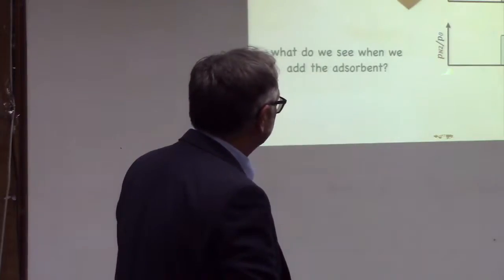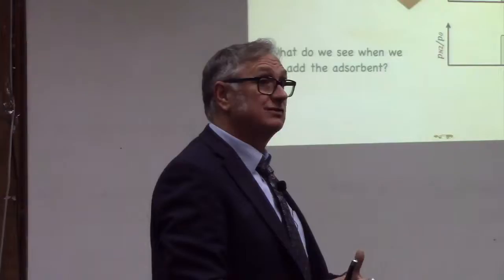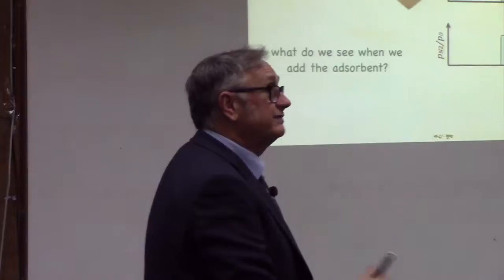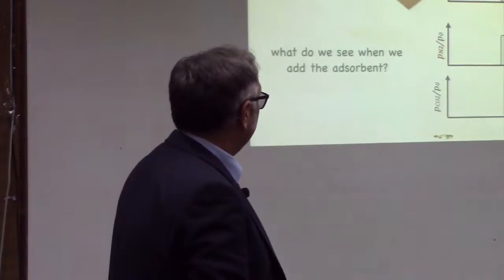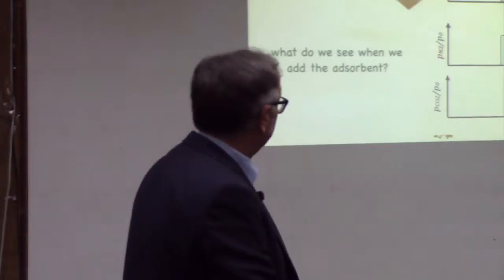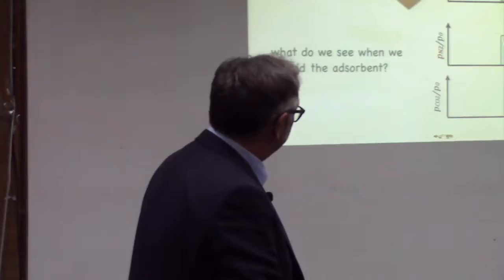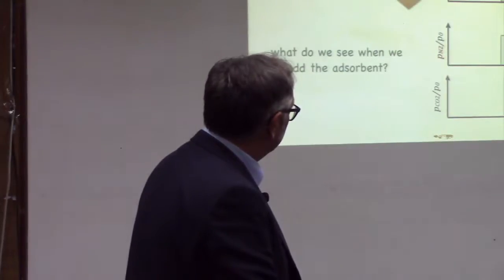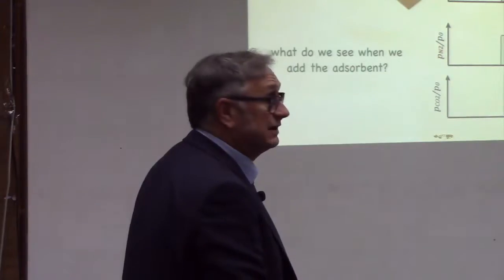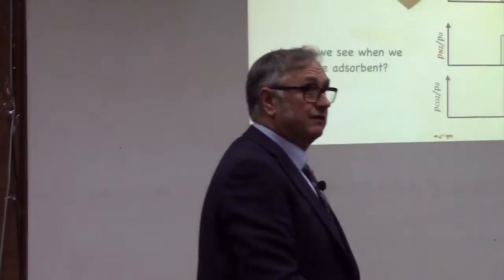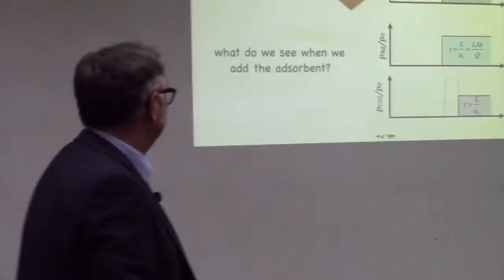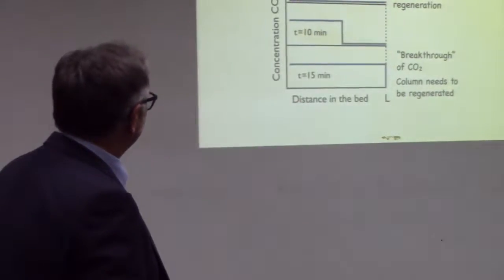Here, for example, is the partial pressure of nitrogen. Nitrogen doesn't adsorb. It passes through just as though there was no powder, with the exception of a little factor having to do with the void volume of the nitrogen. On the other hand, if I look at carbon dioxide, because the bed is adsorbing the carbon dioxide, there's going to be a delay compared to nitrogen. That is, during this window of time here, the packed bed is absorbing CO2 and it's not absorbing nitrogen. And so there's a lag there. So measuring breakthrough curves is a way for us to assess how well the bed is performing when we do the adsorption process.